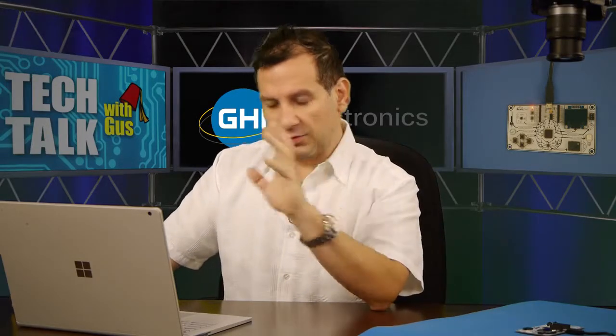Now, this is something that got me very confused, and it threw me off for a couple of days. Using PC6 doesn't actually work. I'm not sure why ST chose to do that. I hope this will change in the future, so PC6 will work. For now, for PC6 to work, you have to convert the pin name to a digital pin. So the pin name is PC6. Digital pin is how Arduino named the pins, like D0, D1, D2, D3, etc.